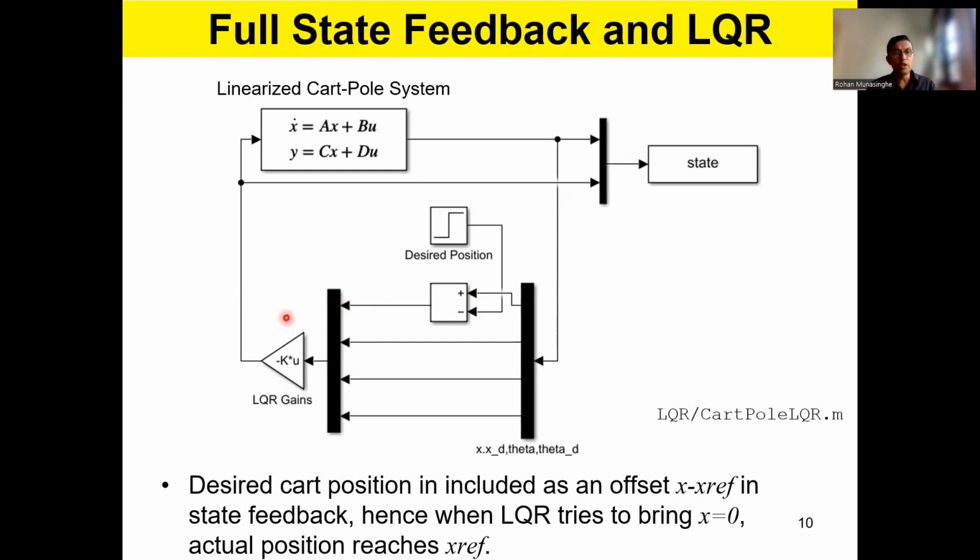It will try to make it 0. So, without knowing what it was doing, the controller will try to make this part 0. When this signal becomes 0, this signal becomes 0.5. So 0.5 minus 0.5, that's how 0 comes over here. All right. So we deceive the controller this way so that it will drive the cart to 0.5 meter. Simple technique.